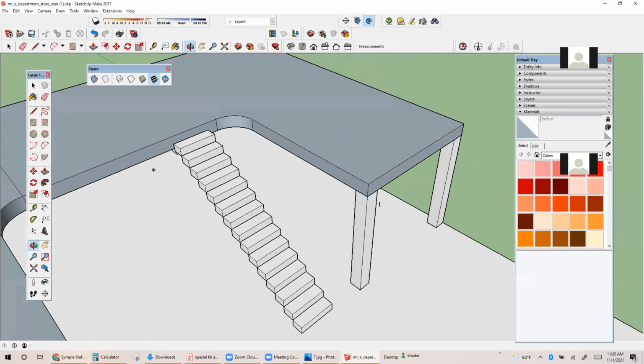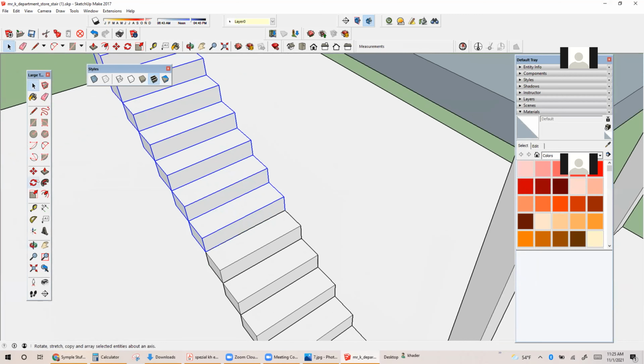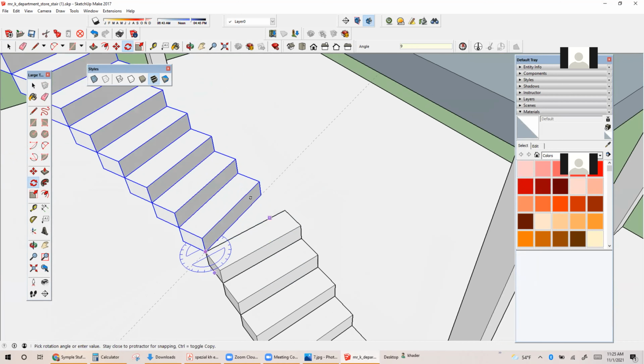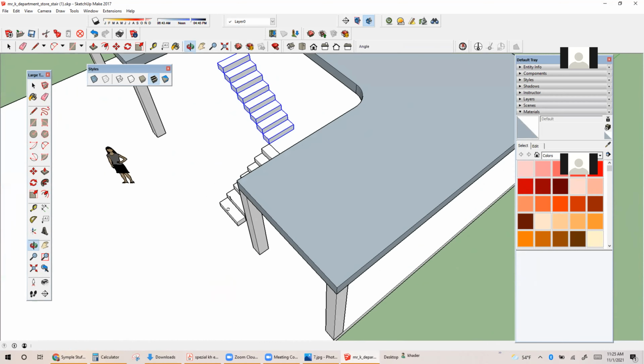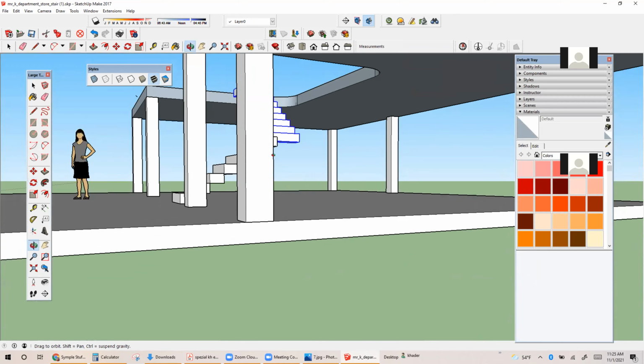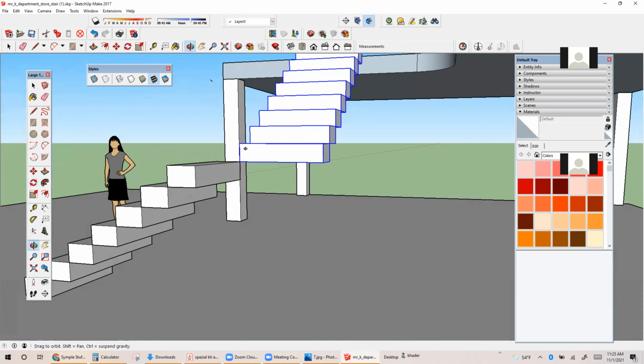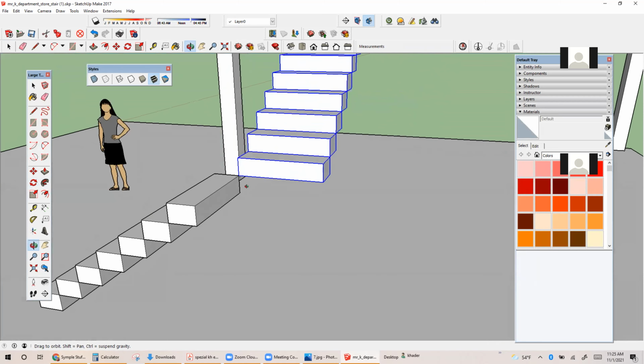So I'm going to break my staircase and create a landing. I'm going to open the upper 8 steps and rotate them. Remember the rotate we used when we did the kindergarten project? So I can make my staircase like this, but now this is dangerous because people will fall and trip through this gap. What should I do? Fill it. We can fill it. So I'm going to draw a rectangle from there to there and push pull.